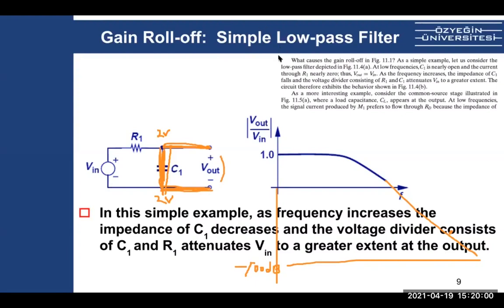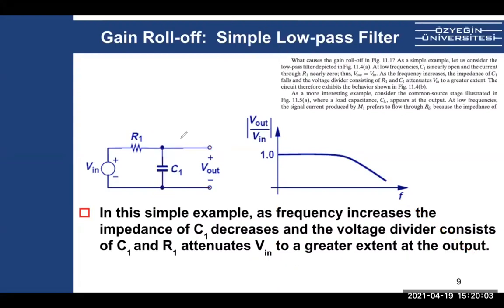If I ask you, knowing this is a low pass, design a high pass, what would you do? Change the resistance and capacitor. I know, okay. So exactly. We gotta reverse this: R should be C, and this should be R. Why? Because for this C, DC cannot pass, right? So this cannot pass, but at high frequency it is short, it can pass. And at very high frequency, this is short. So whatever is here will show here, right? So that's why at a certain frequency now, you get the transfer characteristic of 1, okay? All right.